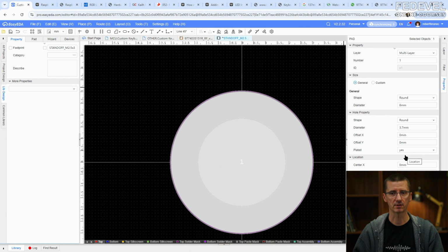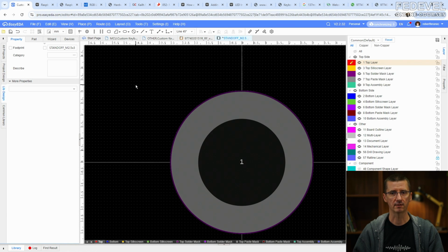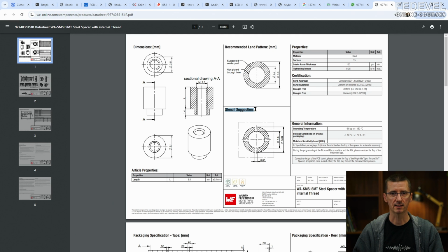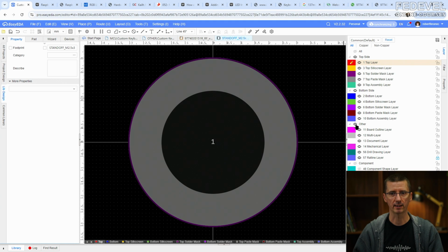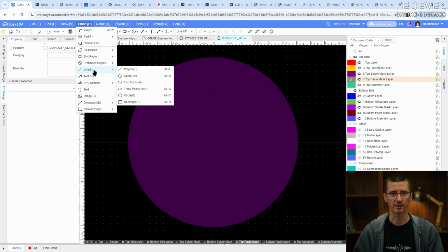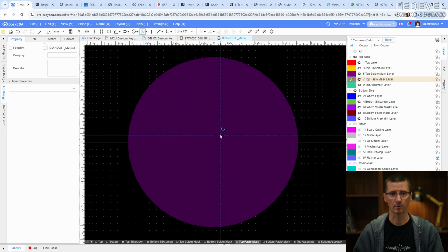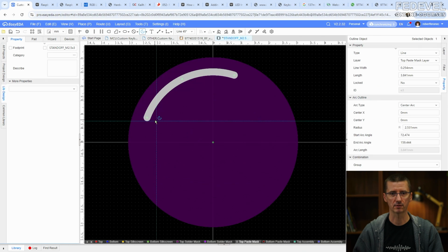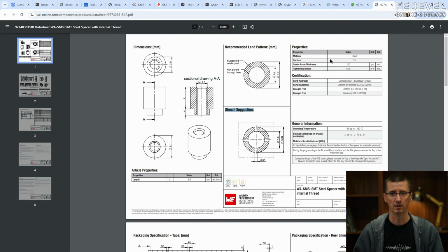I think it will be maybe a little bit stronger. I'm worried that if we only keep the copper at the top, it may fall off from the PCB, maybe, I don't know. This is the stencil suggestion. So this is the way how it's going to be soldered. Stencil is basically going to specify the shape of the solder paste on the top of this pad, and we are going to draw it manually because it has quite a special shape. It looks like these 4 parts.